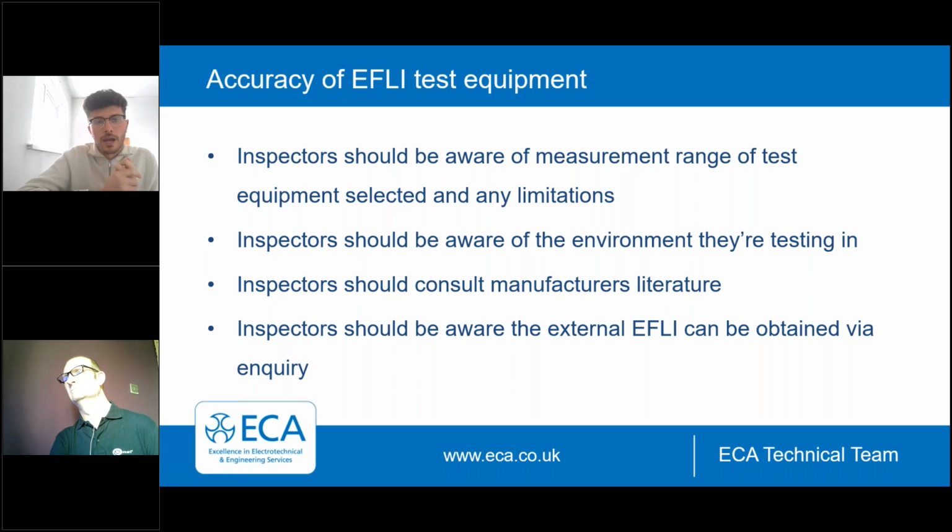So it's something to be aware of in terms of what environment you are testing in. This isn't going to apply all the time. You're not going to need that kind of test equipment all of the time, and depending on the types of environments you work in, you may never need it. But if you are working close to source or at source and carrying out these measurements, then you need to be aware that your test equipment is suitable for such. You are using it as per the manufacturer's literature and within its scope as such.